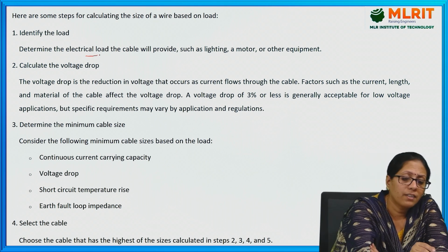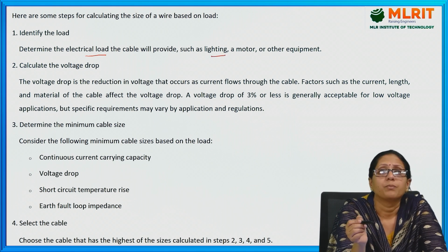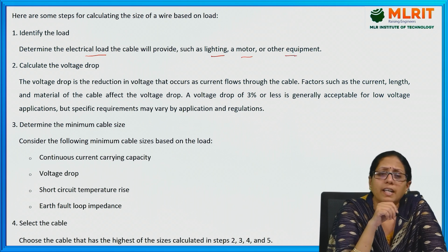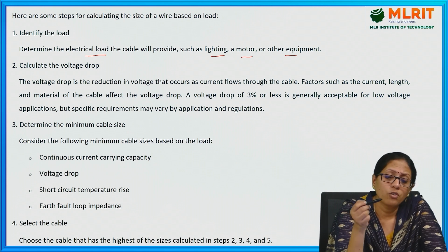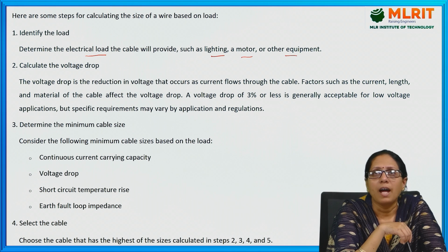Determine the electrical load the cable will provide, such as lighting, motors or other equipment. We can take lights, fans, motors, geysers. So we should first identify the different types of loads and their ratings.